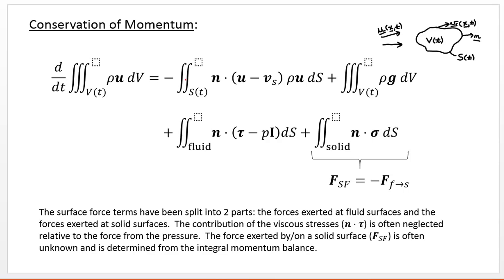And so, as a result, we usually neglect that term there. And then finally, as we've already mentioned, the force exerted by the solid on the fluid, or the fluid on the solid, is often unknown, and it's determined from the integral momentum balance. So typically, we apply this integral momentum balance to determine the force the solid exerts on the fluid or that the fluid exerts on the solid.